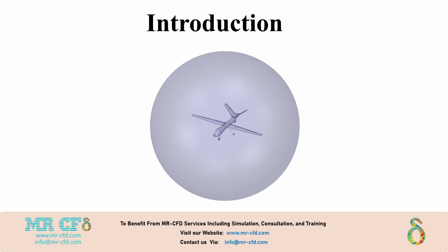You then treat the enclosure as fluid, air, water, etc., and the original part as solid. The enclosure's outer faces become your domain boundaries, inlet, outlet, far field, and its inner face coincides with the part's surface for heat and momentum exchange.